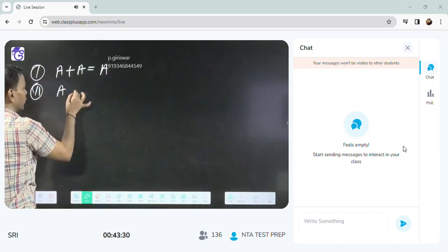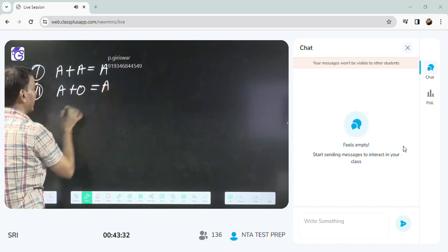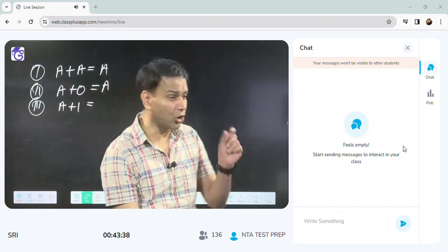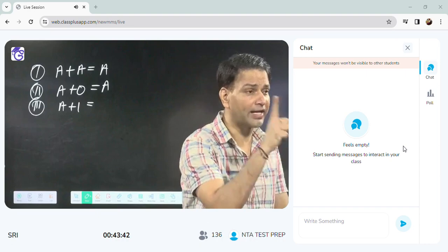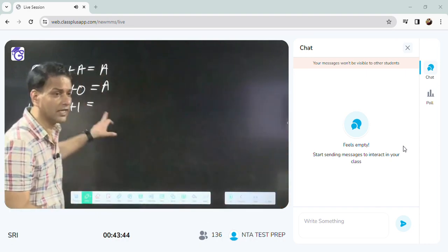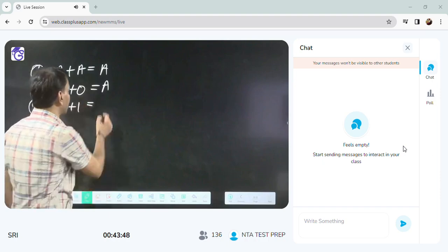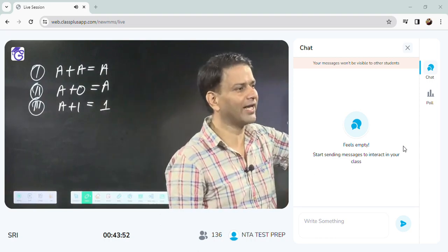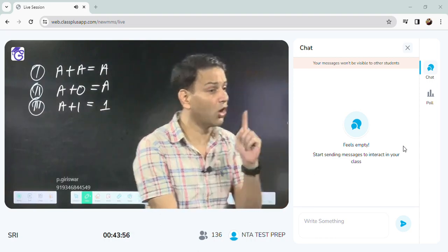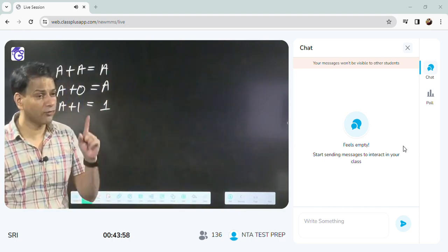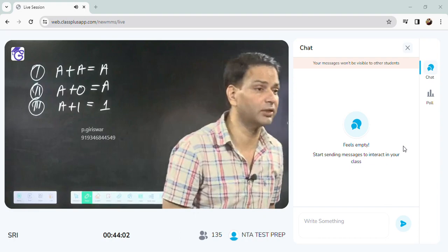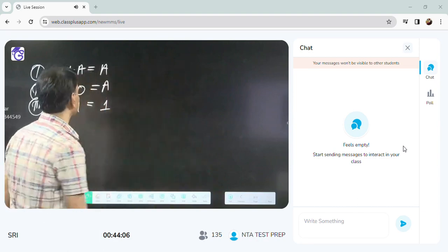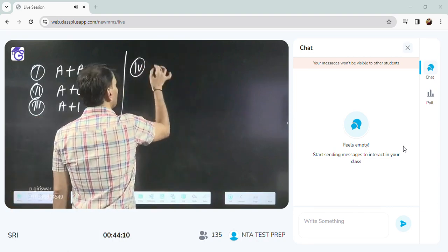Second, A plus 0. A plus 0, then directly what will you write? A. A plus 1. In the OR operation, if any input is 1, then no need to think about the other. A plus 1, no need to think about A. Directly I can write 1. So anywhere I am getting A plus 1, whatever the value of A, A bar, B bar, if one input is 1, OR will always give 1. In the case of OR, we will get 0 only in the one case when both are 0. If any one is 1, no need to think about the other. Directly we will write 1.